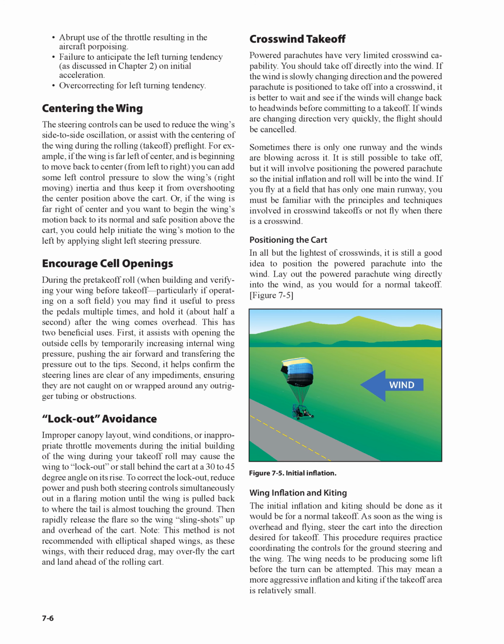This procedure requires practice coordinating the controls for the ground steering and the wing. The wing needs to be producing some lift before the turn can be attempted. This may mean a more aggressive inflation and kiting if the takeoff area is relatively small.